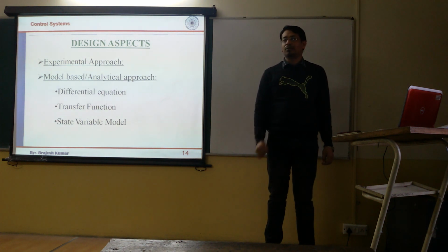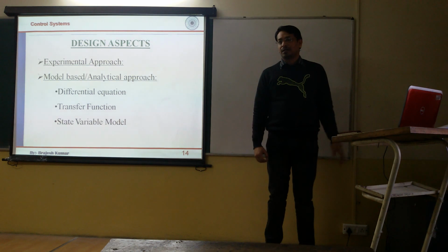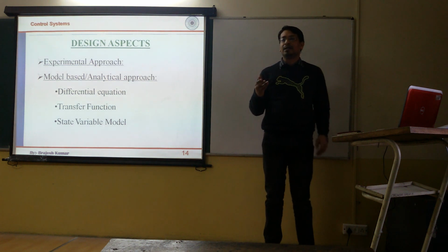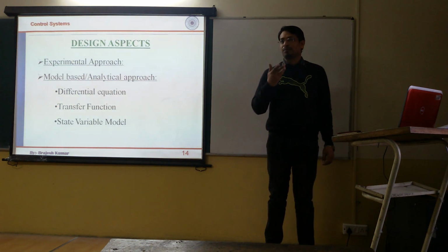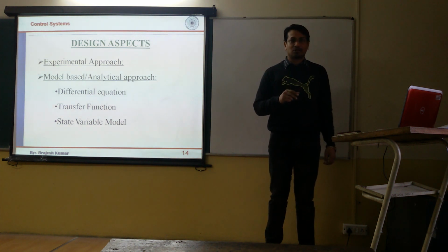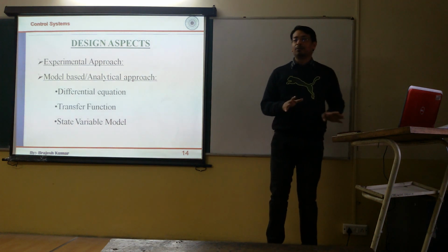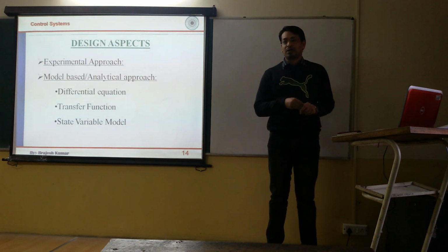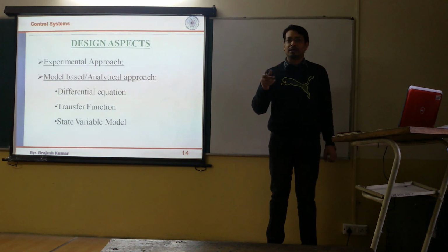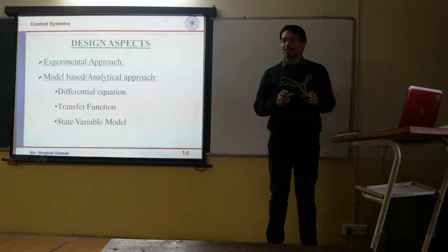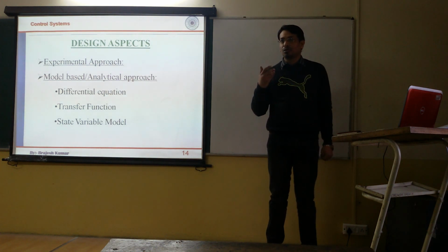You will also read about this in your third year in process control. Some Ziegler-Nichols methods are there, and some other methods for tuning. And in experiments also, if you do a PID controller, you will somehow apply this method of controller tuning. So this is a simple approach. You can say it is an ad hoc approach, because for a complex system it is not going to work, because tuning will continue for infinite time. Suppose 3 or 4 variables are there, adjusting all of them to get the desired output is a very difficult task. So this works fine for a simple system, where the requirements are not so hard to meet.